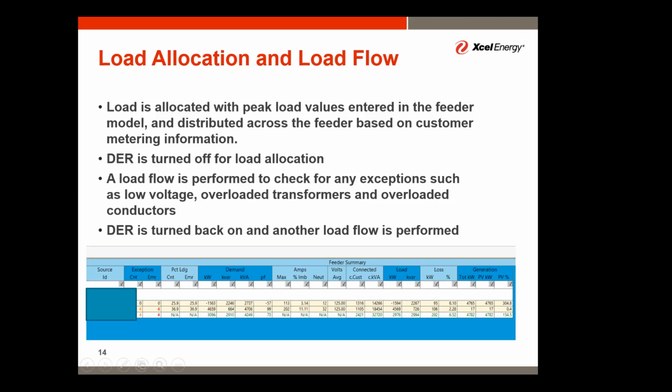I will highlight below the output of a load flow. This is just a summary. There is, again, much more to be seen here. But we can see we have 2 feeders, and then this is the summation of the 2. Feeder 1 is experiencing quite a large amount of generation. We have negative kW backflowing into the feeder head with a total kVA of 2.7 MVA. Feeder 2 has about 4.7 MVA of load on it. And again, it's a fully loaded feeder. There's no backfeeding generation here.